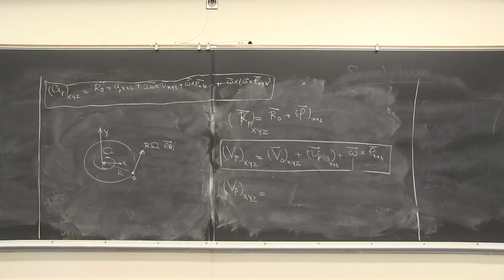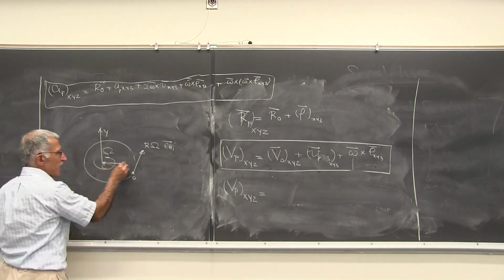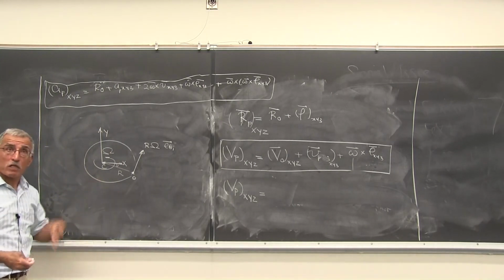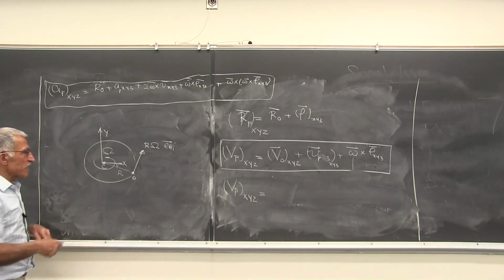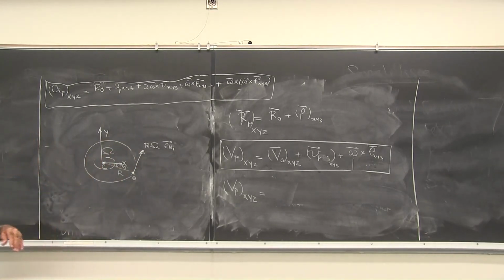E theta 1. So that is the velocity of the point. And of course, if you know this angle at this instance, let's say it is 30 degrees or pi over 3, you should theoretically be able to say what the direction of that velocity is. Forget about the arm, and it has some velocity in this direction. You can do it at any instance, you can put it as a function of theta, and say at this instant theta is here, and that's the velocity at this instant.